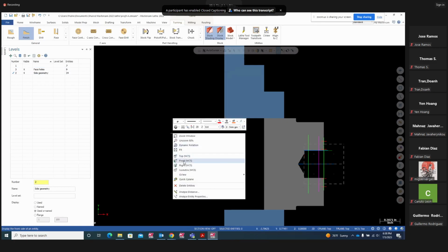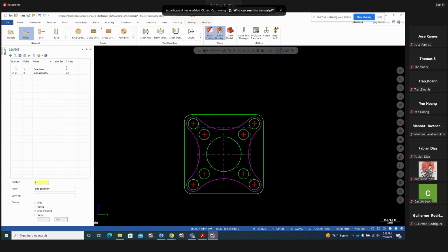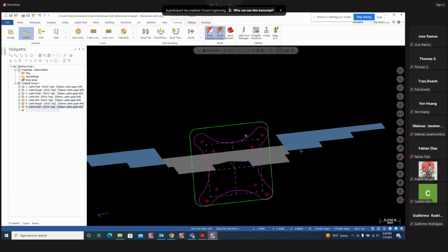Go to construction plane right. And now we're going to work on this area. Here comes all my C-axis stuff. That's where we're going to go ahead and contour on this guy, and drill the hole. I don't need to see the circles either, guys. I can just go to level, and I can turn the face holes off also. All I need is the point for the center of the hole to drill the holes on the face. So this is what we're going to work on now.